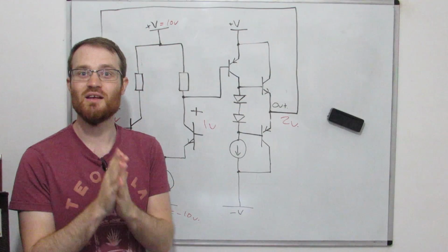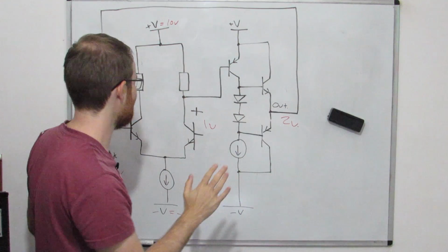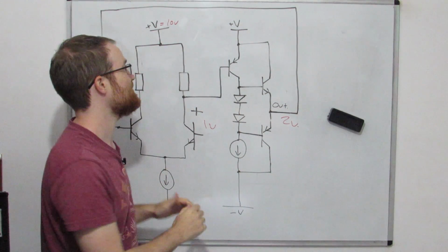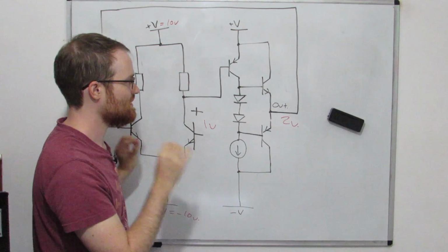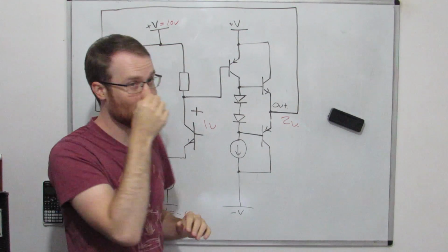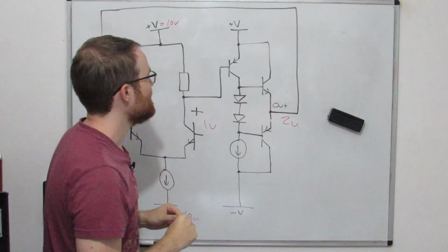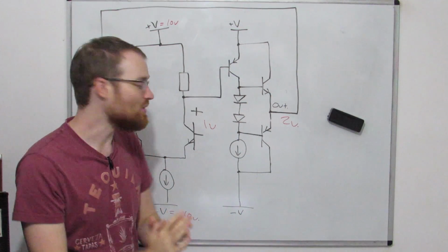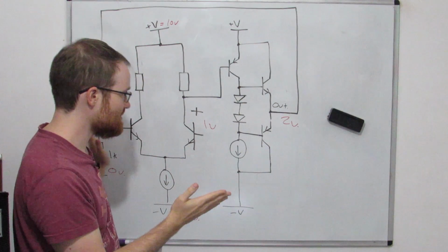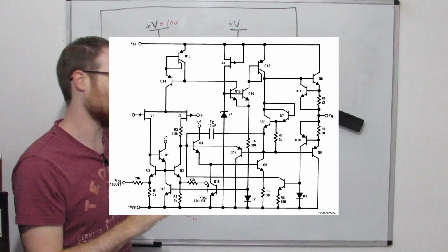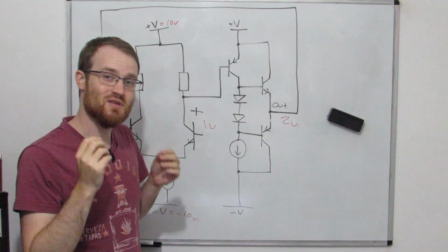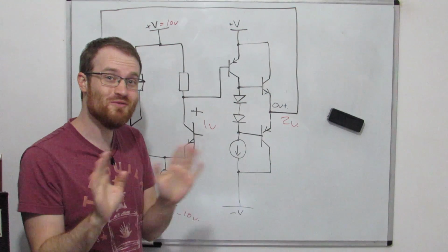Okay, so the important thing in this video is that we've looked at this and we've convinced ourselves that we can approximate this op amp as a high gain differential amplifier with a low impedance output buffer. Now that I've hopefully convinced you that that's true, we can do something that's very important. We can look at this, even just this simplified schematic and definitely the detailed schematic, and go, there's a lot more to it than that. But you see, what's important is that we don't care.